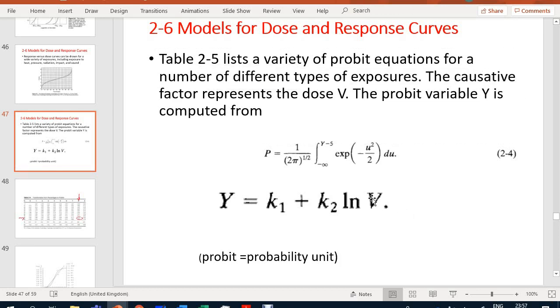It's the causative factor, and it could be different when we talk about, for example, emissions of certain gases or ppms. Here we are talking about certain causative. It's calculated as a summation of concentration multiplied by time, and this concentration could be to the power 1 or to the power 2, whatever. We are going to solve problems with that. So going back, we are calculating the Probit.